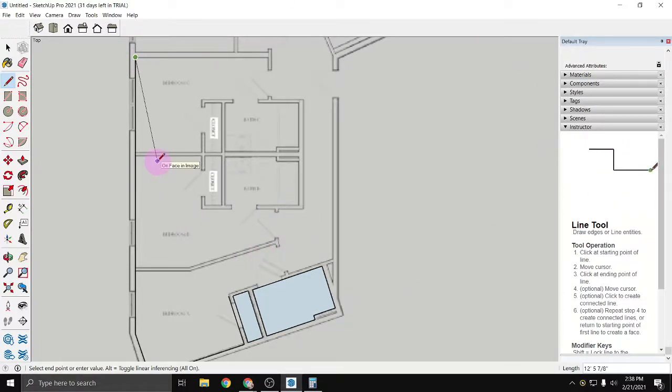Or if maybe you only have a view of the outside, and it's a picture of the outside of the building, but the building has bricks on it. Well, the other thing that you typically know is that bricks are about 8 inches long. They're a little shorter due to the mortar joint. But even then, we can just add the mortar in with our little calculation, and you read the number that you have, and then you figure out what number you want it to be, and then you divide the measurement you want by the measurement you currently have, and then you can scale your drawings so you can get a nice little reference.